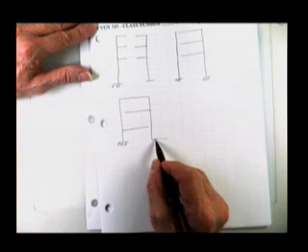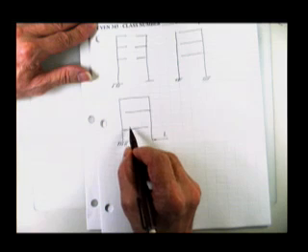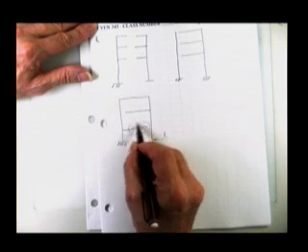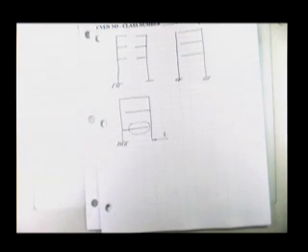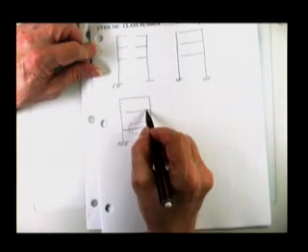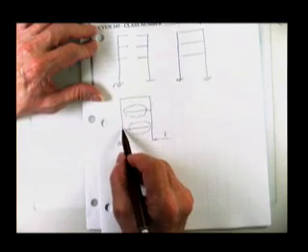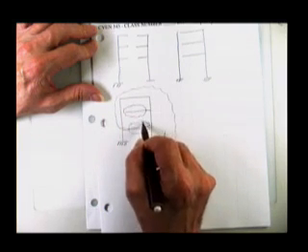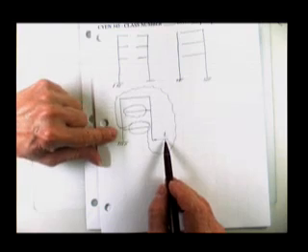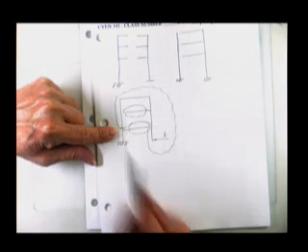For instance, if you say, well, I don't believe you, I'd like to put a 1 right there, and I'd like you to tell me what the moment is right here. Well, all you do is you cut this piece off and you draw a free body of it, and the answer is what? 0. There's no moment on it. If you say, well, how about here? Well, that's fine. I'll cut that right there. The answer is 0. And you say, well, how about right here? Well, now then the answer is not 0. Now then the moment is 1 times this height right here. That's how much moment is at that point.